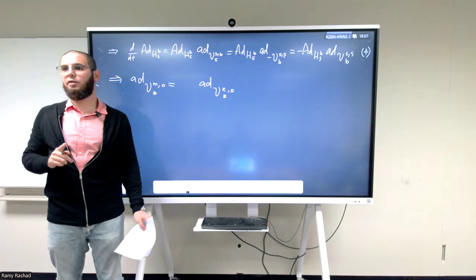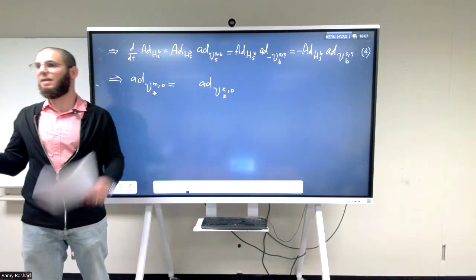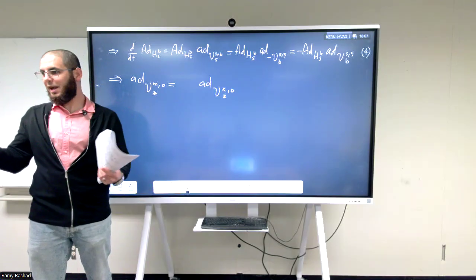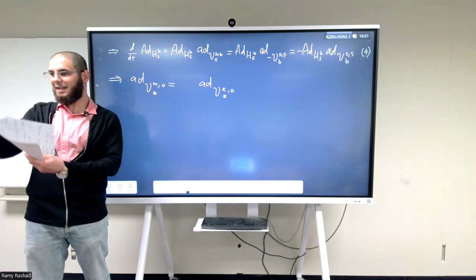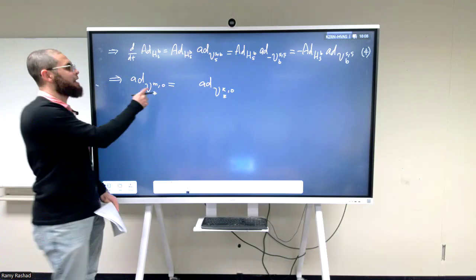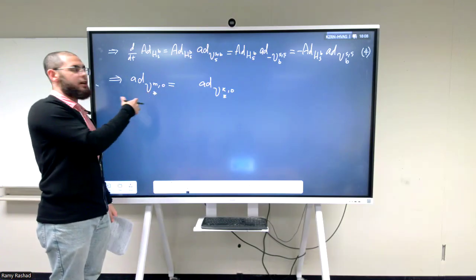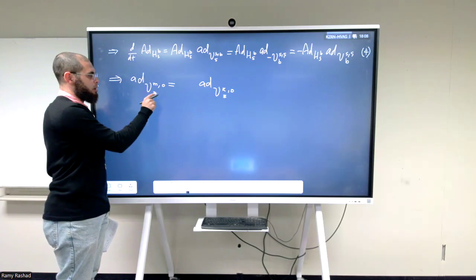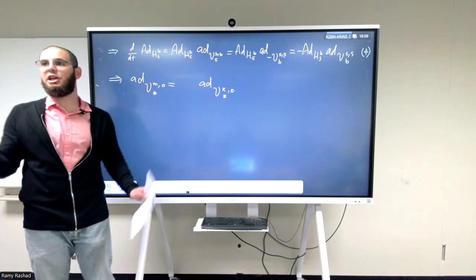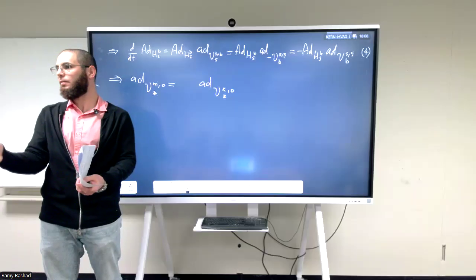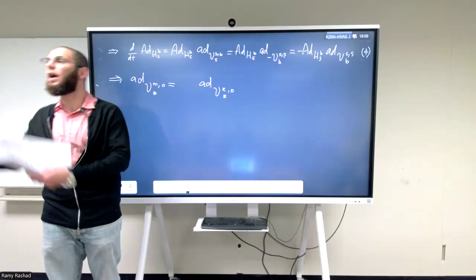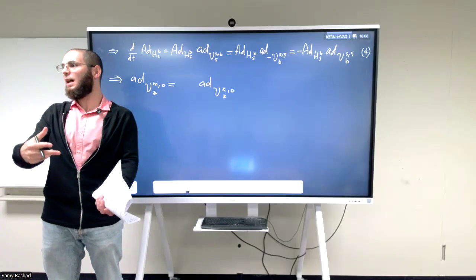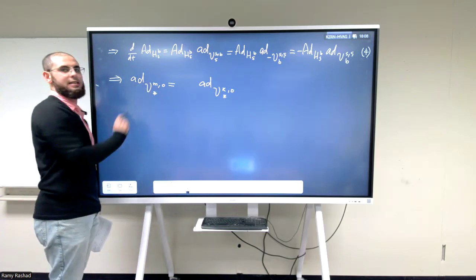Because that's only the observer. You remember what we said about the abstract concept and the components? The abstract vector itself does not change. It's exactly the same abstract vector, which here is the relative twist between the body attached to frame star and the body attached to frame O. It's not changing coordinates. It's something that's abstract. Only what's changing coordinates is where I express these coordinates. This is the only thing that has the basis. And that's why this is the index that changes.